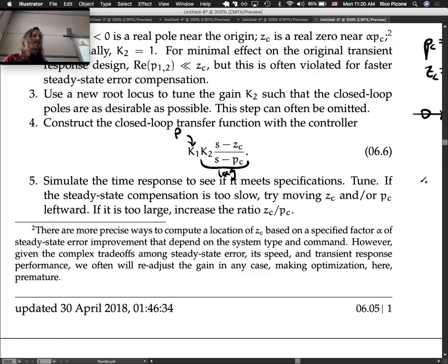And then maybe there's a differentiator, maybe there's an integrator in there. You estimate that with some numerical approximation of a derivative or an integral by, say, summing up errors over time for an integral and taking the difference over time for a derivative term. And then you multiply it all out till you get your voltage that you want to apply to the motor, and then you go through a digital to analog converter and amplify it and deliver it to the motor.